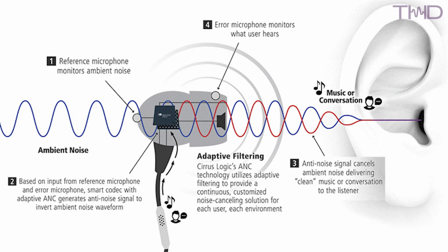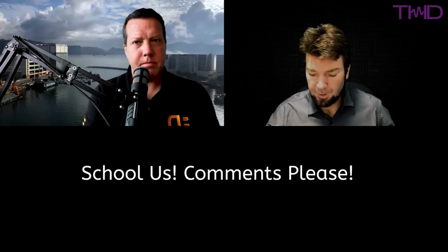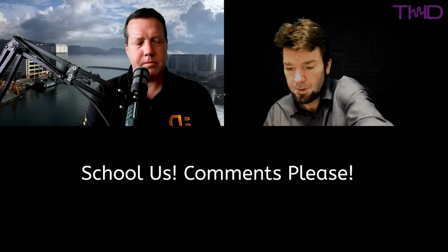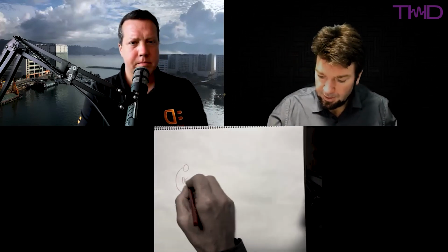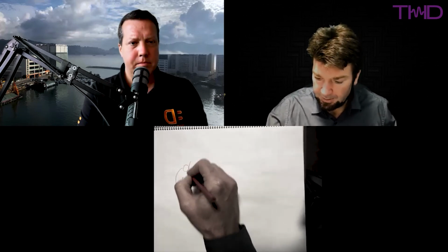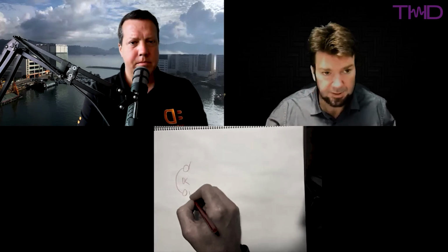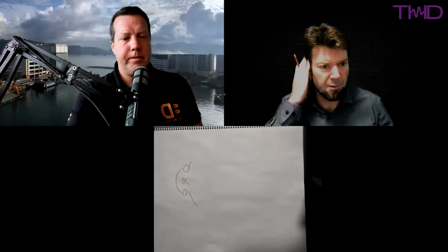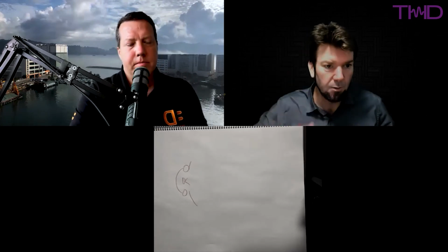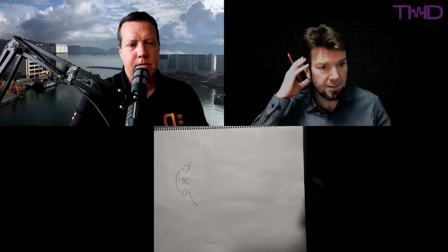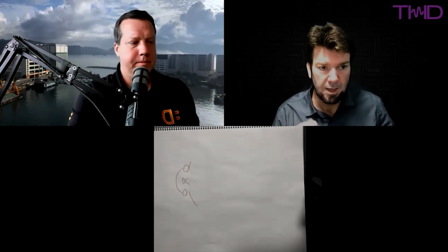Slightly different concept. I don't know adaptive very well, but enough to say, in that feed forward diagram, the response of the speaker, the sound that you get out, is very much dependent on how well sealed it is on the air. So if you have leakage, your low frequency drops off a lot. If you're familiar with that, if you break the ear pad on a headphone, all the low frequency is gone. It requires a strong seal, right, to get the low frequency.